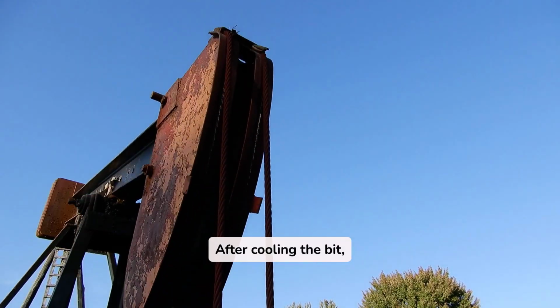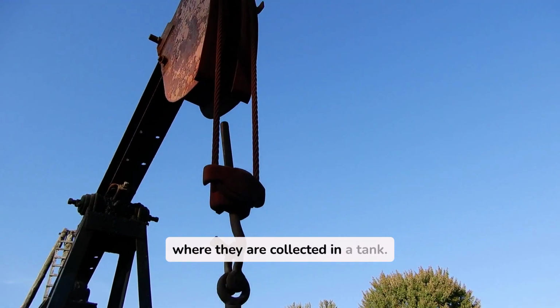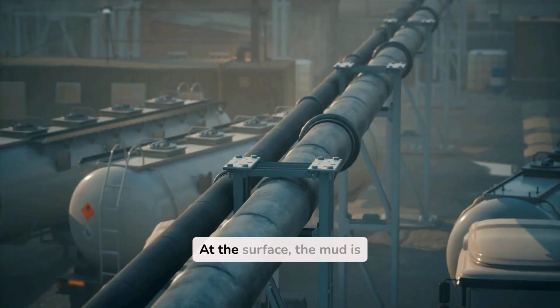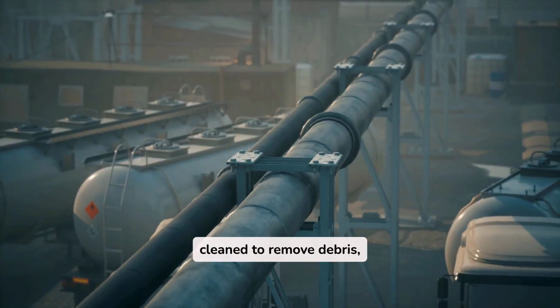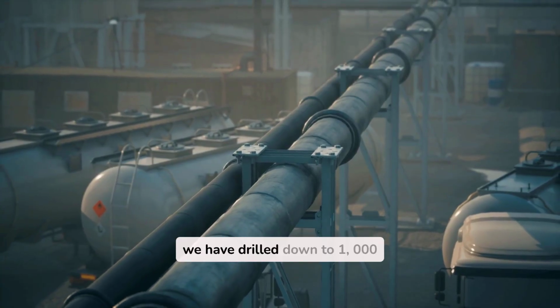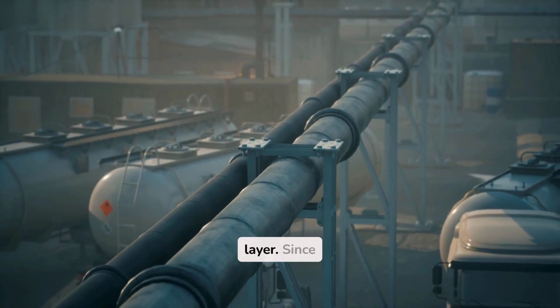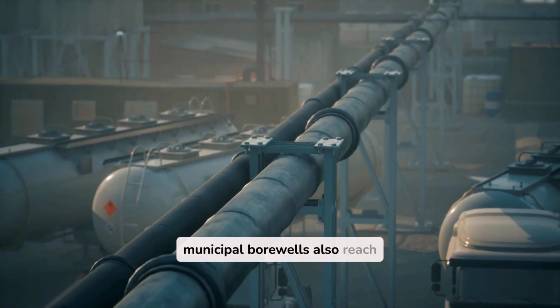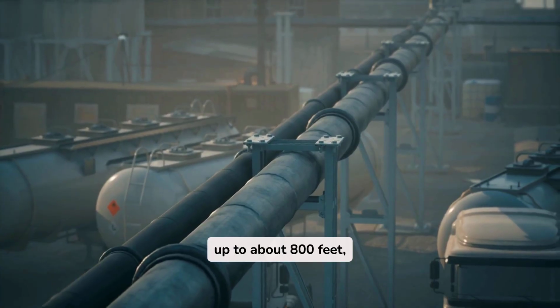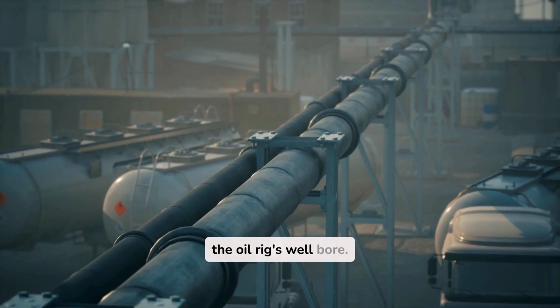After cooling the bit, this mud carries the rock cuttings back up to the surface, where they are collected in a tank. At the surface, the mud is cleaned to remove debris and then recirculated back into the wellbore. Suppose we have drilled down to 1,000 feet and encounter a weak layer or a water-bearing layer. Since municipal borewells also reach up to about 800 feet, it is crucial to ensure that no water or debris enters the oil rig's wellbore.